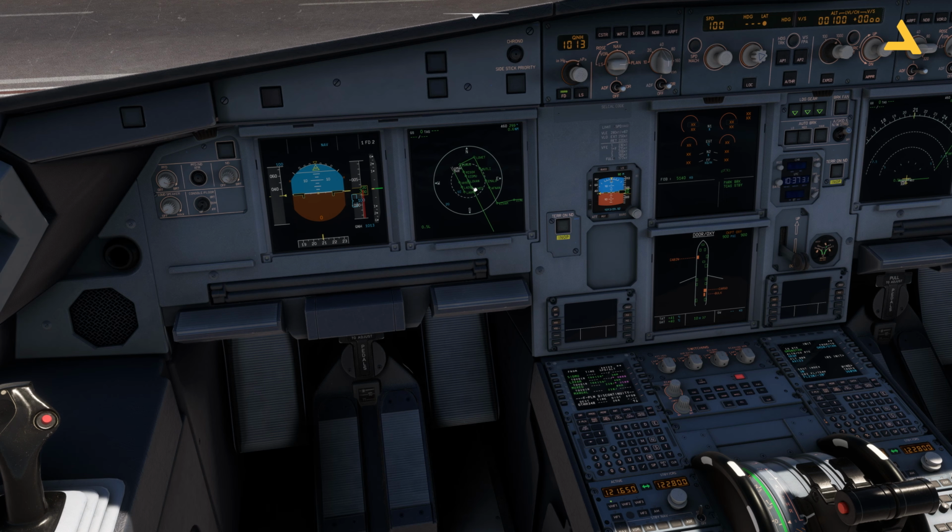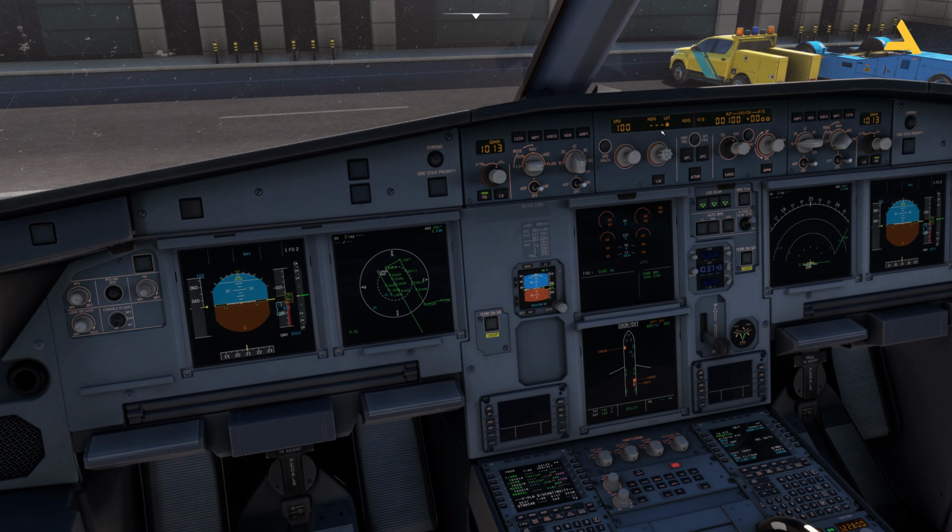So after the discontinuity, if you do not do anything, if you don't fly in the heading mode, the plane will actually keep on going straight and it will not turn right towards the approach. So over here at this point, you have to actually then fly in the heading mode. Right now this plane is in the manage mode. You can see this is the heading selector, and there are 3